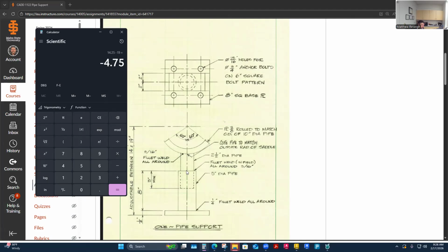has got to be 4 and 3/4 plus the 3 inches. This gets confusing, right? This is the way my head thinks. If your head thinks differently, what I'm looking for is how long to extrude this thing so that I maintain 3 inch minimum telescoping and hit 19 inches of adjustability. Well, I think I need to have 4 and 3/4 there plus my 3 inches. So I've determined that this length from here to here is 4 and 3/4.